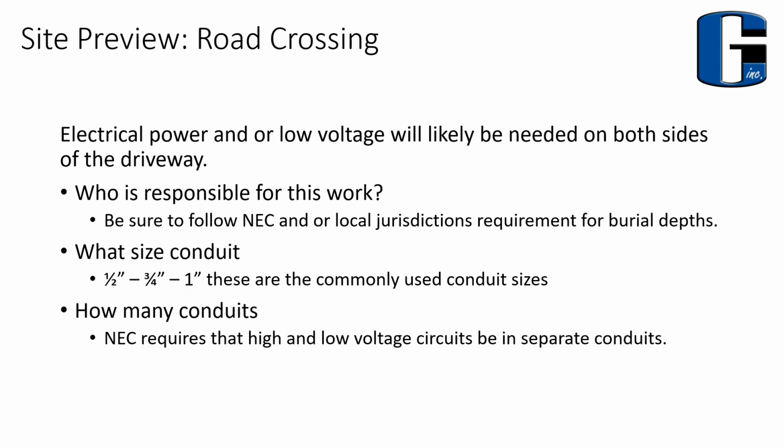Electrical power and or low voltage will likely be needed on both sides of the driveway. So who's responsible for this? If that's a lot of work, if you have to do a road crossing, it could involve a lot of trenching. It could involve maybe trying to bore a hole underneath the roadway, saw cutting, very expensive. Be sure to follow your NEC and your local jurisdictions or requirements for burial depths.